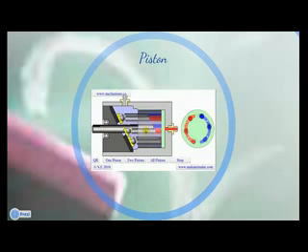The cylinder barrel looks like a revolver's barrel, and the pistons are located inside this barrel just like bullets. The rotation of the barrel forces the pistons to rotate with the barrel. The round ends of the pistons are connected to the yellow shoes, which slide on an inclined black swash plate.